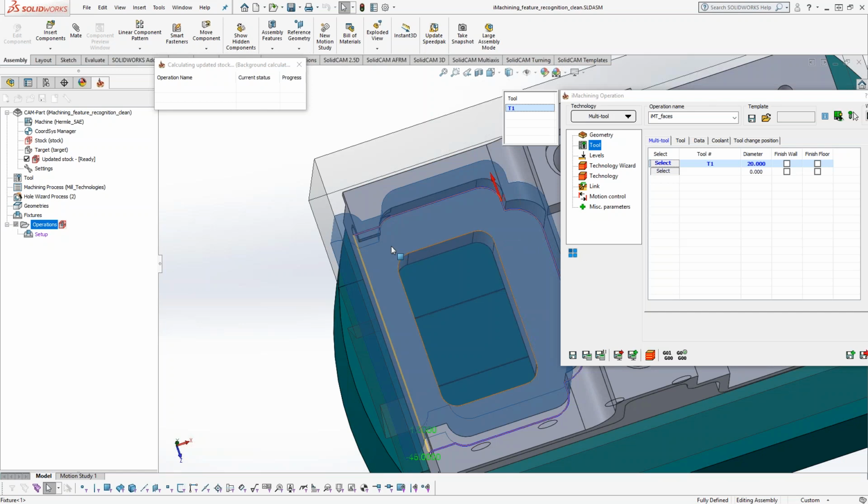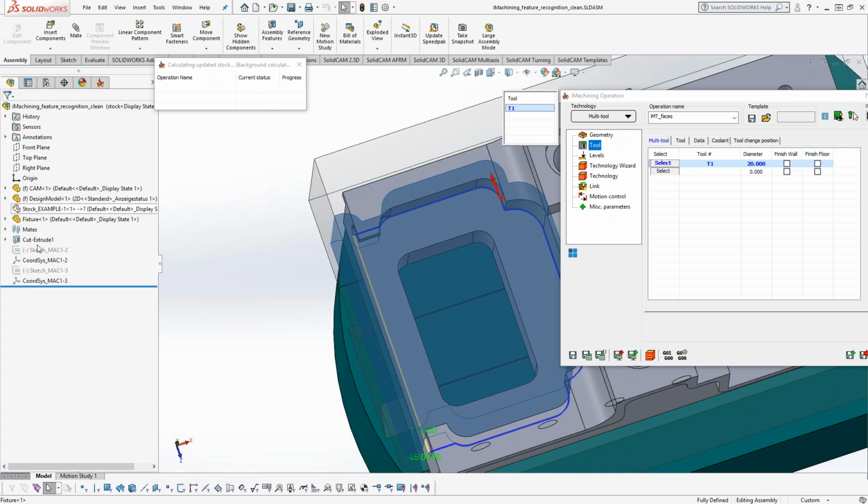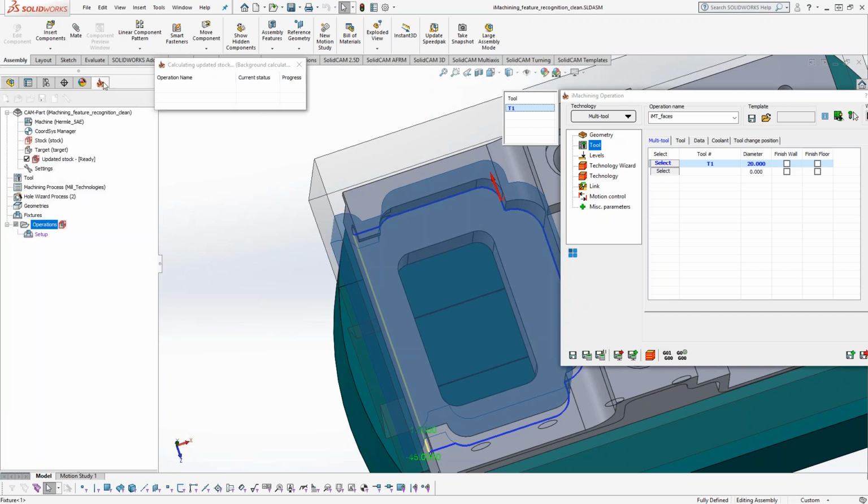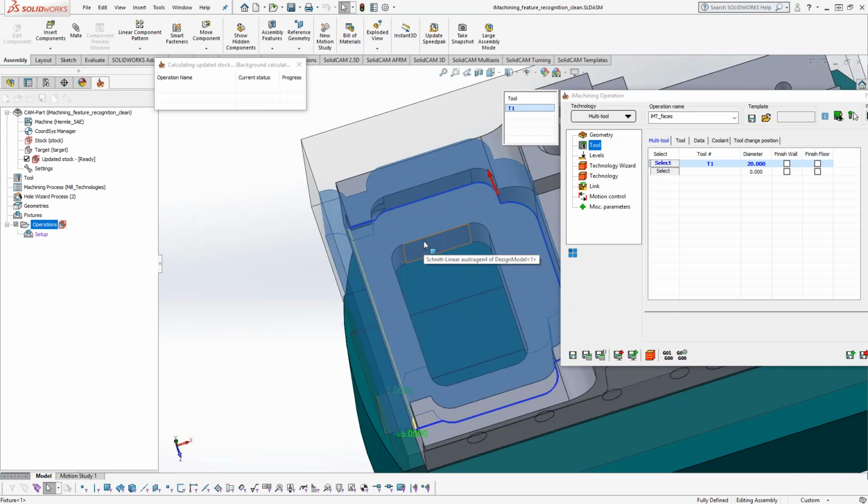If the customer was doing that manually in SolidWorks or in Inventor, then you would end up having to fix their sketches all the time. And I think we've all seen customer files where for every geometry they have in SolidCAM, they have a sketch over here for each geometry. That way they can be very organized and very clean, and if they need to modify it, they can deal with that. So with the new feature recognition, you get away from having to do that.